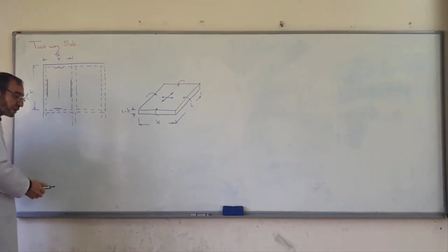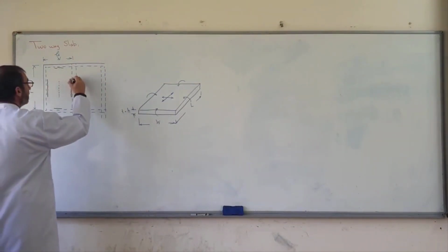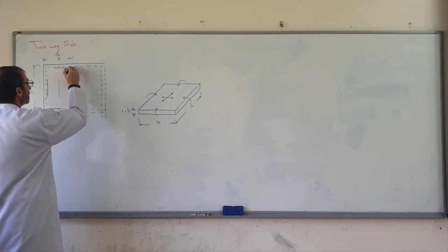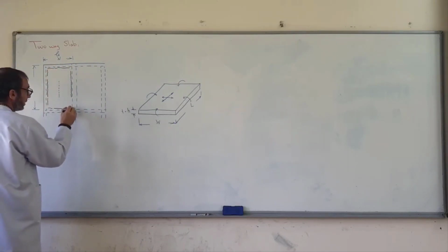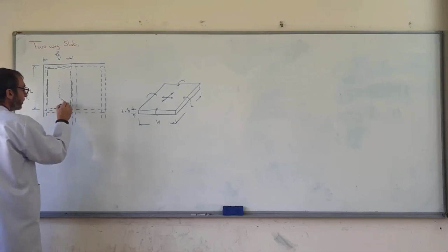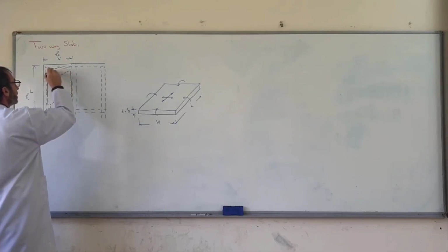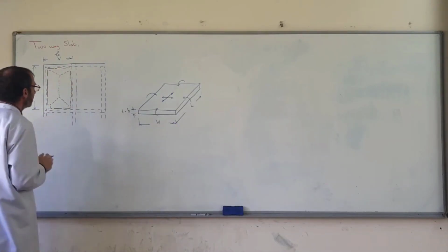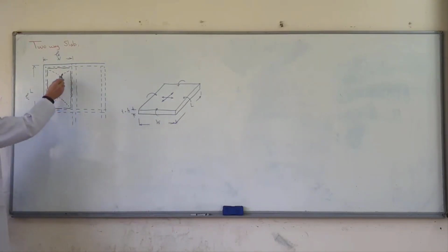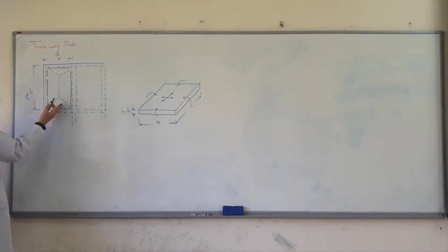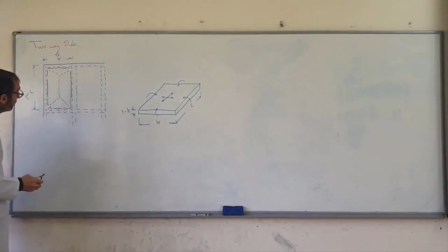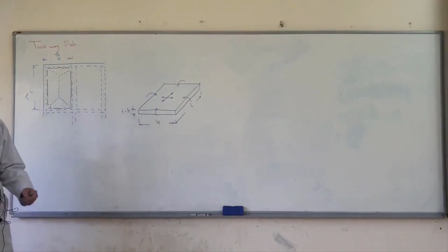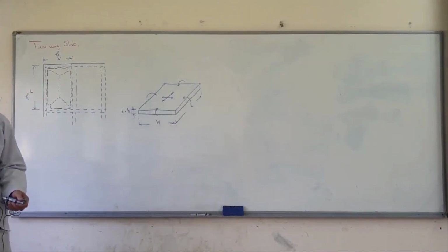After that, if we still increase the loading, the behavior goes this way. At the top, cracks continue, and at the bottom sometimes they go here. This certainly depends on the dimensions of the slabs. At the bottom, failure appears in a line; failure occurs in this way. This is the behavior of the slab under a uniformly distributed load.